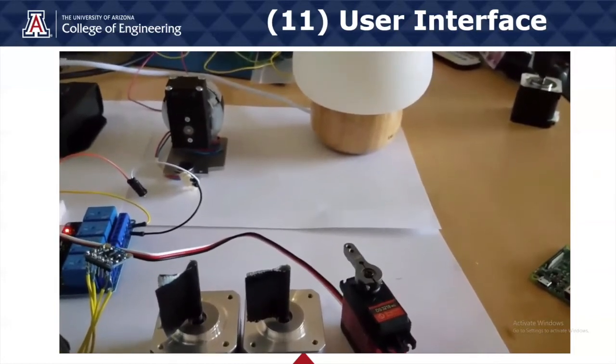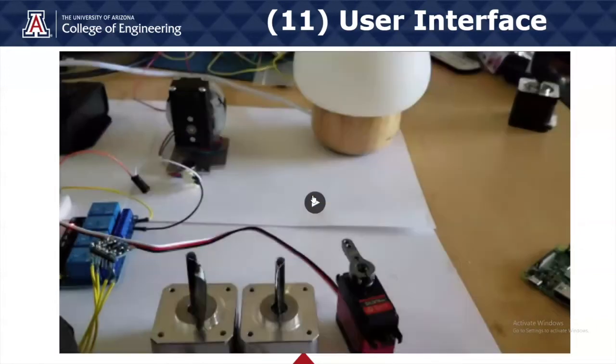The servos then move a certain distance at the same time. This represents the clear cover rolling up and the re-roll pulling the tape a specific distance so that the next sticky pad is in line to have an iButton placed on it. When my hand or an iButton is moved, the feeder bowl turns on again and the motors stop until a new iButton signifies that the feeder bowl rail is full and ready for an iButton placement.